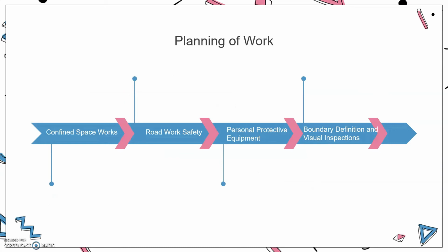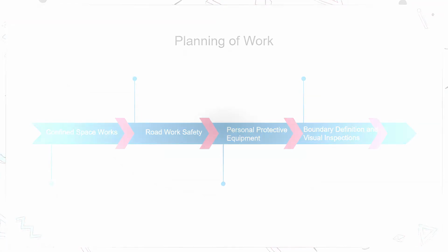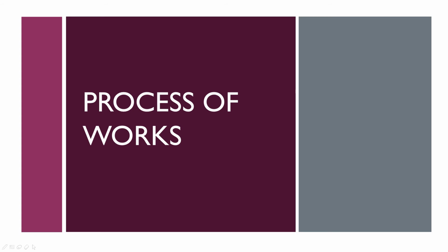This is facilitated by the use of a total station and arbitrary control points, where possible manholes, valves, vaults, and chambers will be opened in order to map their extent and depth. Now, the process of works of underground utilities for survey and mapping.